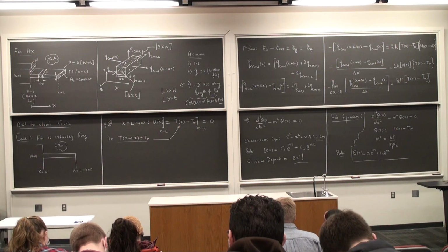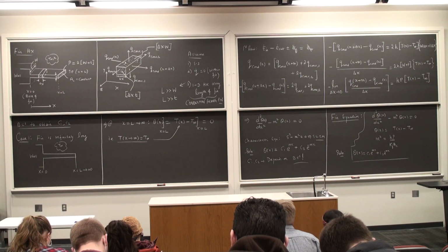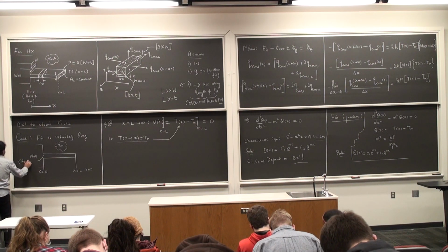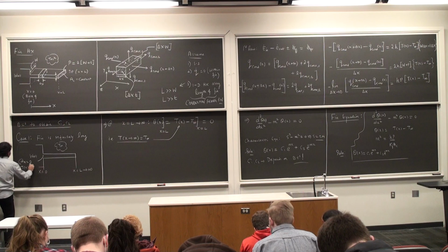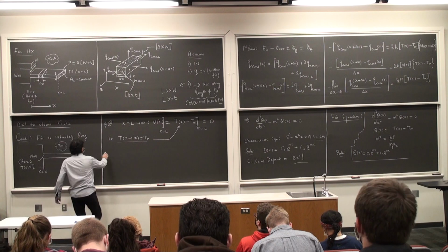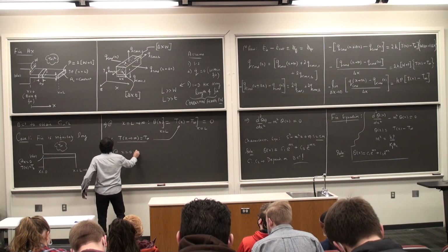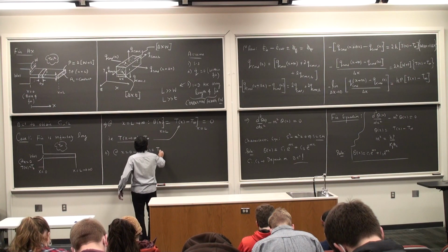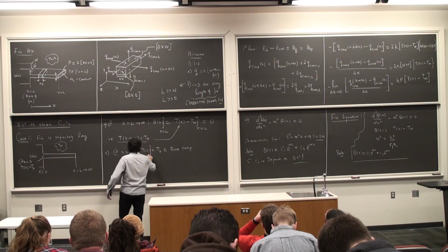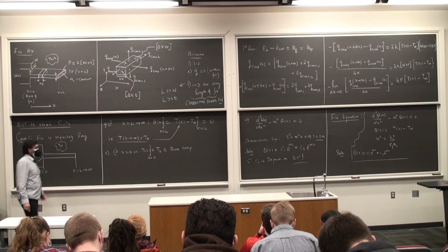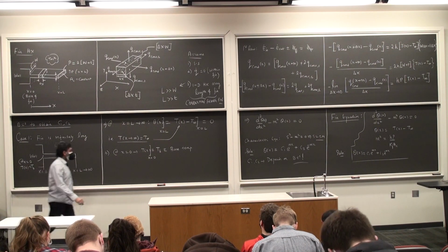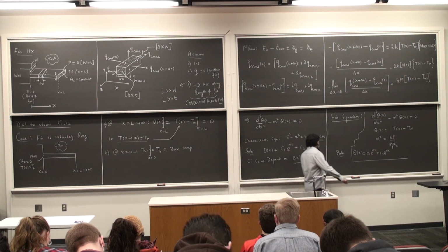That's my first boundary condition. My second boundary condition, this is typically prescribed for all the fins: the temperature at the base of the fin will be prescribed. So at x is equal to 0, T of x is T suffix b, little b is the base temperature of the fin. Okay? So the second boundary condition, at x is equal to 0, and it's a simple matter of just substituting these boundary conditions, solving for the coefficients C1 and C2, which gives you a very elegant solution, and which makes complete physical sense.